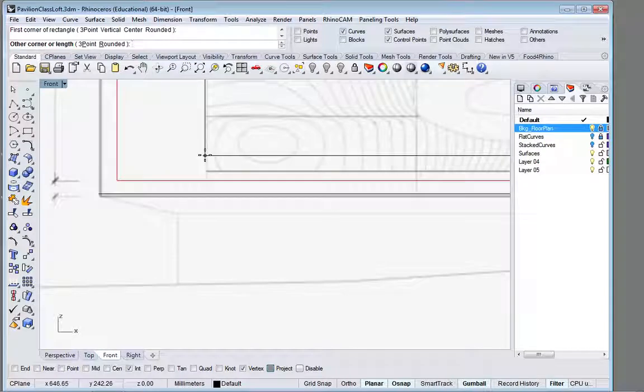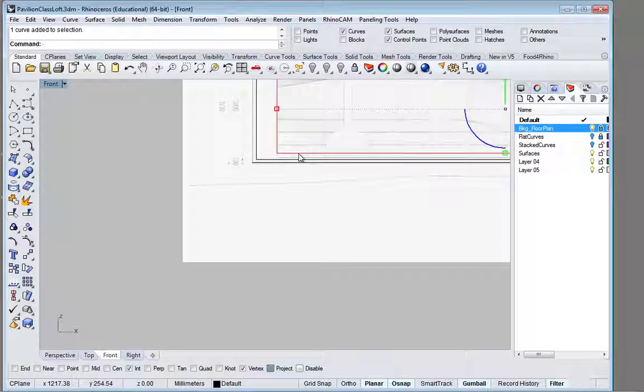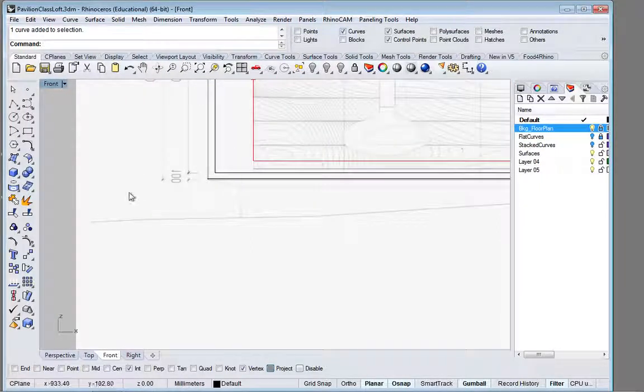Alright, so I'll show you a different way. When that doesn't work, you can always click here. So I'm just going to make it close. So I have it, and I know that I need to move this down. So I'm going to turn on the control points by clicking over here in the corner where it says Edit Points On. I'm going to turn that on, and you'll see that now I can select this point.